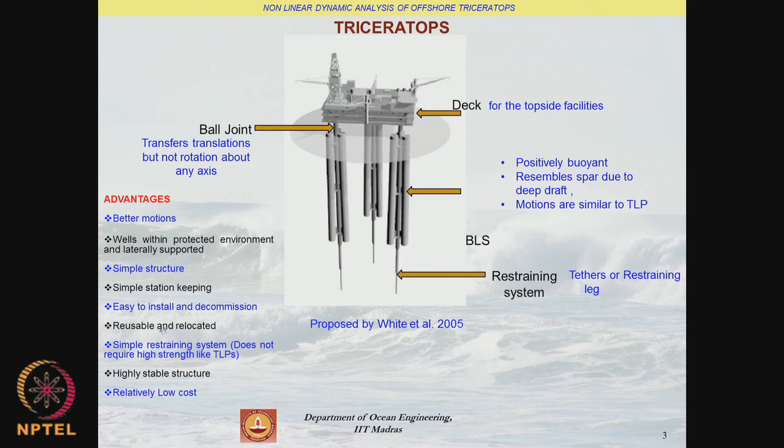platform, highly reusable and relocatable, simple restraining system, does not require a high tether tension as in the case of tension leg platforms, very highly stable because of a positively buoyant system, relatively low cost because installation and decommissioning is very fast with the lowest possible downtime.